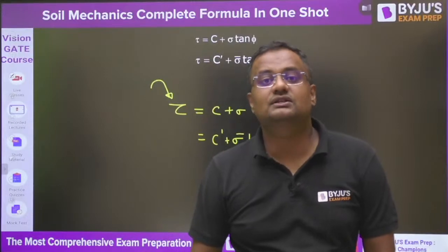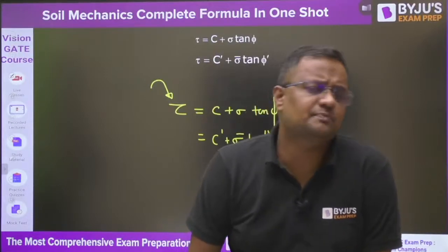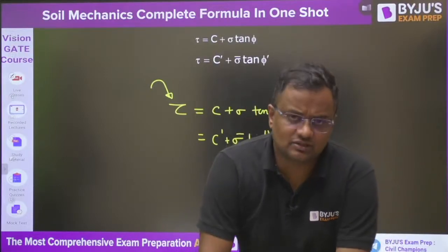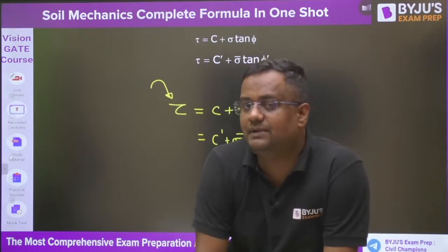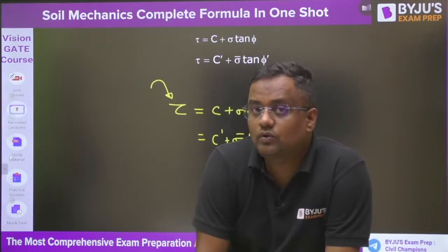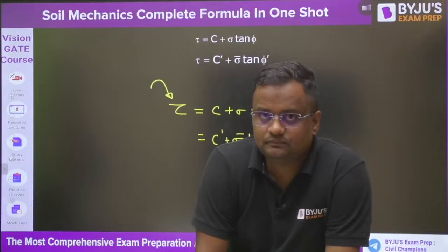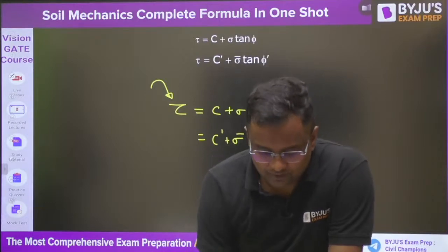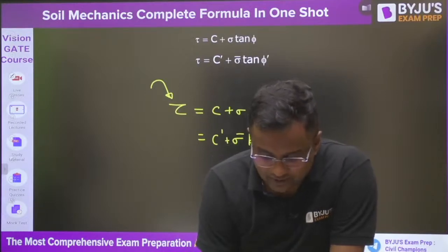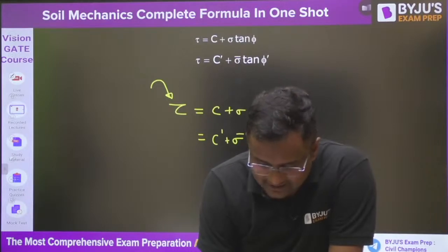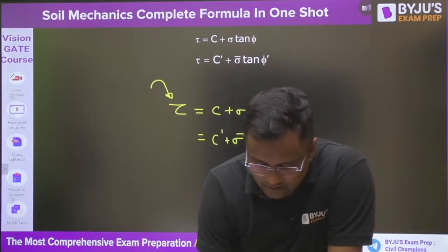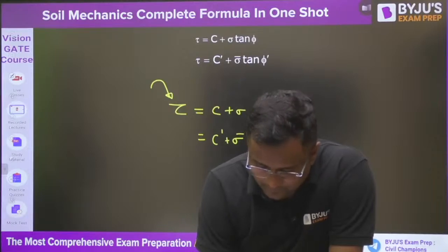Like if the actual condition is clay, that has very less permeability, that is undrained condition. So while finding C and phi in the sample, we should provide undrained conditions there. Okay, so we should be doing it like this, simulating the field conditions, so that C and phi come according to the field.